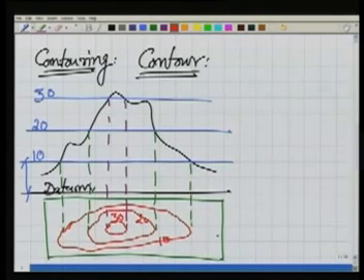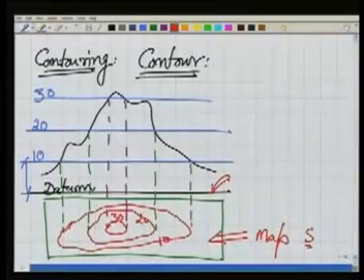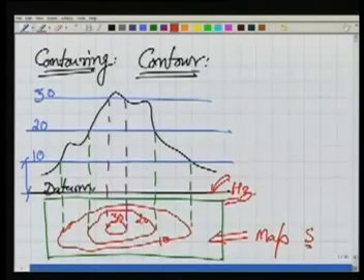This is a map, and it will have a scale. At this scale, this map which has these lines, which we call contours, is called the contour map. So we are able to understand the concept of the contour by this. There is one more important thing. I said that the datum in this case is a horizontal plane. But is it really a horizontal plane? As we have discussed, our datum should not be a horizontal plane, rather it should be an equipotential surface.